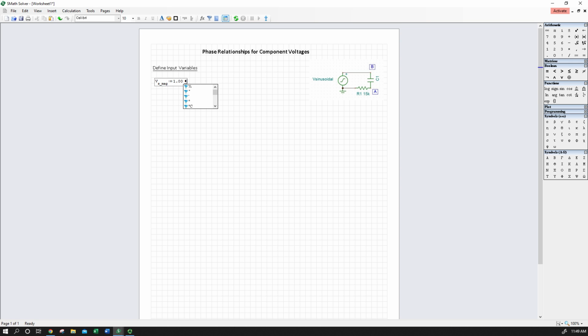So when I do that, I end up getting a little indicator with a drop down and these little blue symbols that says, hey, what variable would you like? What type of unit? So I'm going to type in a V, and you can see it gives me all kinds of selections, but I want volts. It's very important that you double click on that selection. Don't just type a V and assume it knows it's volts. So you have to actually select it from the library. So I double click, and you can see it's in blue. It says volts. So now I know, okay, it definitely knows what I wanted.